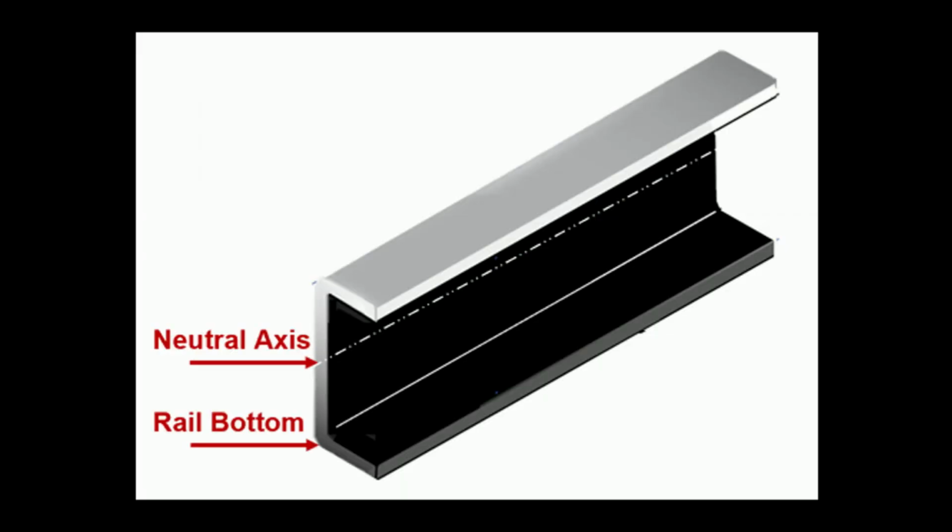Most truck components are mounted off the side or web of the channel shape. Drilling holes through the flanges is strongly discouraged, as this can compromise the rail's structural integrity. Manufacturers often place warning labels on the frame to caution against welding to the flange. However, some bodybuilders weld subframes to the rail flange to increase strength, especially when mounting equipment. While not manufacturer approved, this practice is common in certain applications.